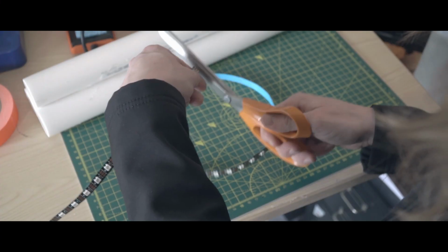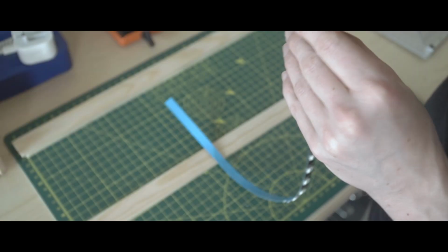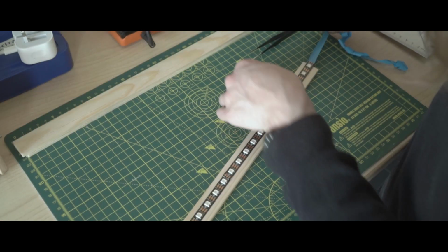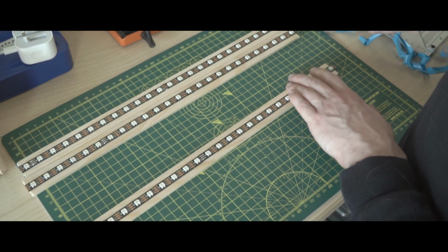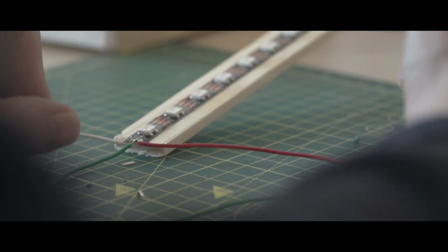Sorry. Once trimmed to size, installing the LED strips was pretty simple. These strips come with a layer of adhesive on the back. So all I had to do was remove the protective film and carefully apply 3 LED strips to 3 lengths of strip wood. I then soldered 5V, ground and data lines to the input end of each strip to power and control the LEDs, before hot gluing into place inside the PVC pipe.